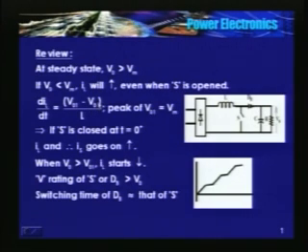Now during transient stage VO is continuously changing, okay. So and VO is less than VO1, so di by dt is still positive, it increases, maybe slope will not be the same. So in the second cycle again I am closing the switch, current increases.